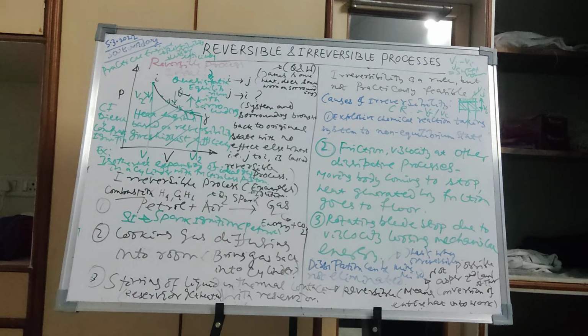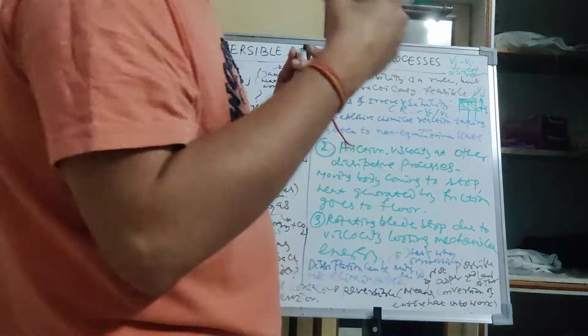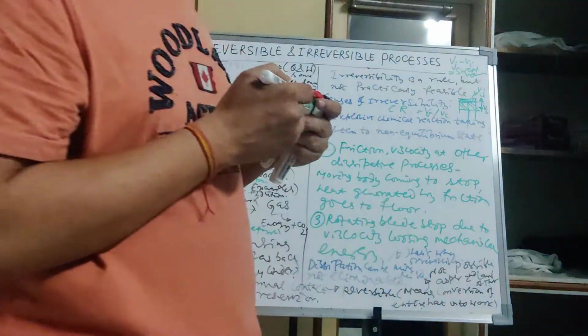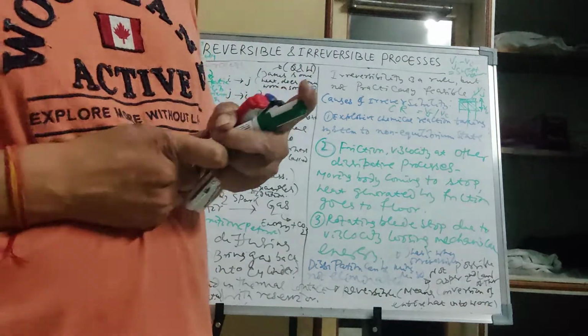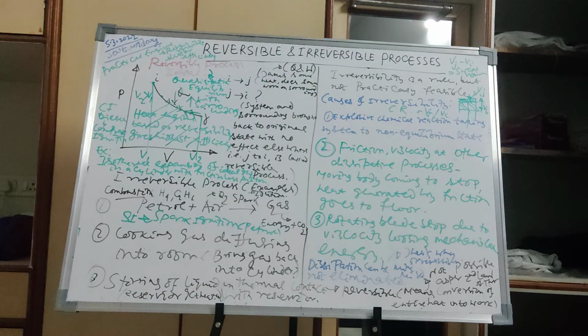So what happens because of the spark? All of a sudden, the pressure and temperature increase because you are putting some heat energy there. Let us say the air is getting compressed here. After it is compressed, it is already high temperature, high pressure air. When you inject fuel there, all of a sudden combustion starts. When combustion starts, some heat energy is released, so you are adding heat there. If you add heat, the pressure and temperature of that gas increases. There is a sudden explosion happening.